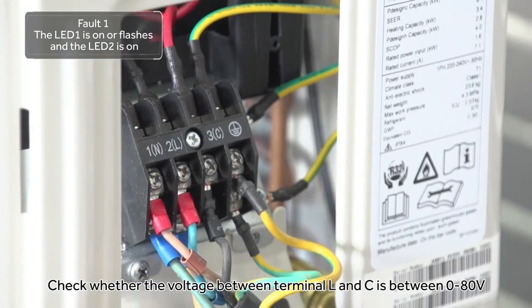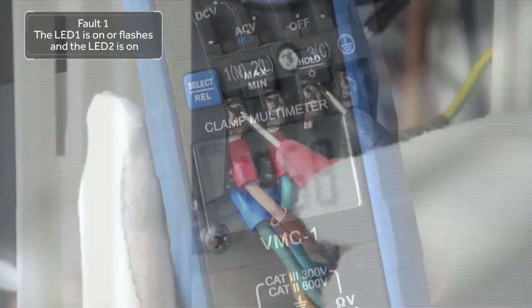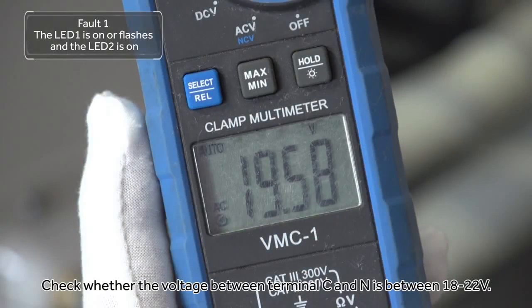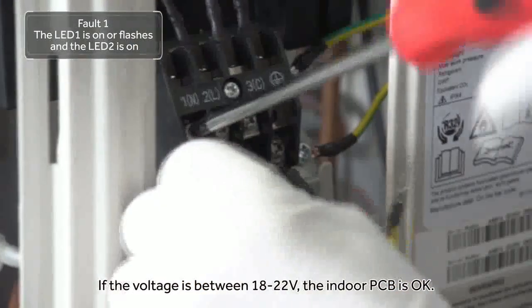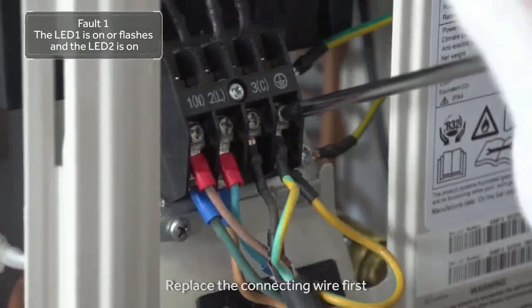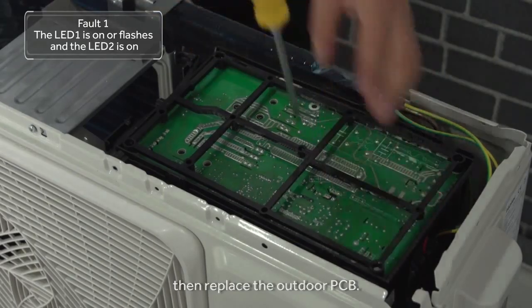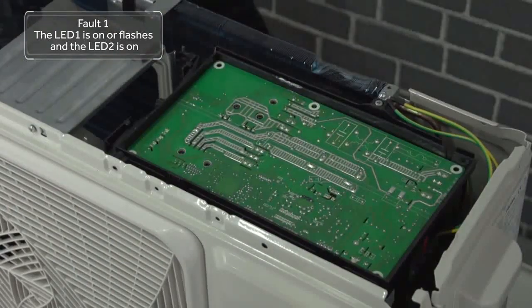Check whether the voltage between terminal L and C is between 0 and 80 volt. For the super match product, check whether the voltage between terminal C and N is between 18 to 22 volt. If the voltage is between 18 to 22 volt, the indoor PCB is okay. Replace the connecting wire first. After that, if error code E7 still exists, then replace the outdoor PCB.